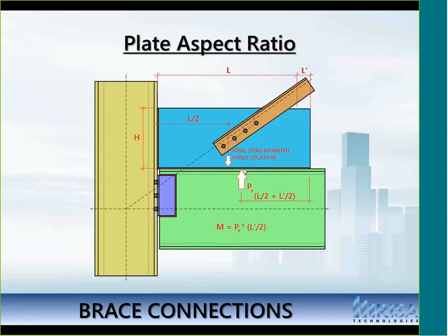And so you'll get the same forces running through your connection, but with an added moment that's going to occur at this location. Now, you could certainly also look at it the other way and say if I change my H in this connection, then I'm offsetting the horizontal force that's occurring between the gusset plate and the column. That would then have a moment arm, and so then we would see a moment that occurs due to that.